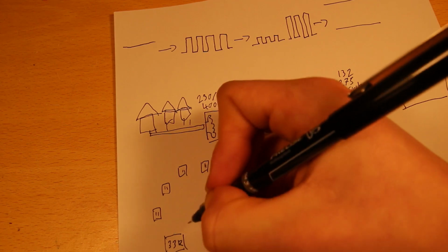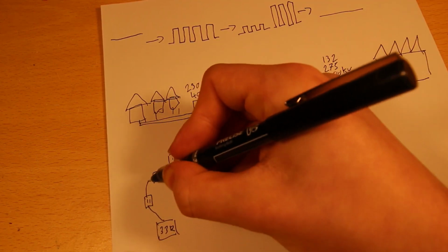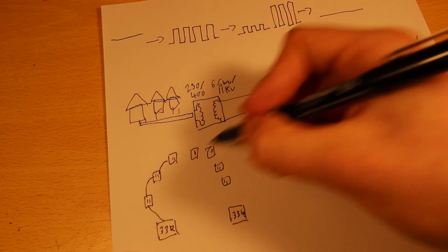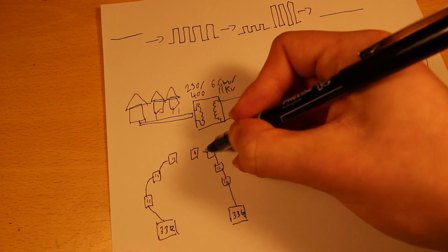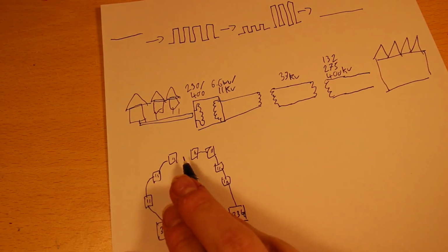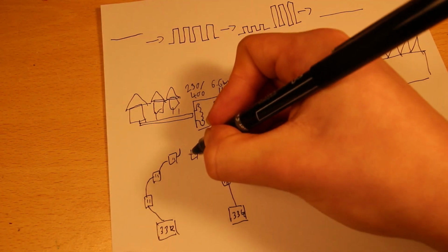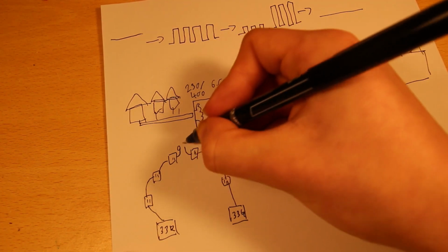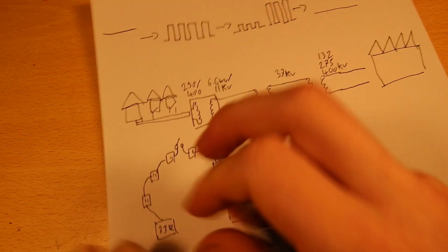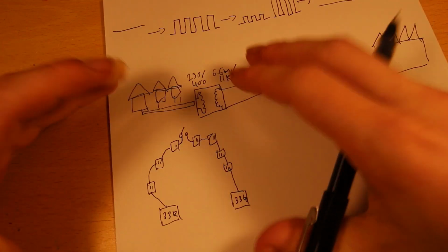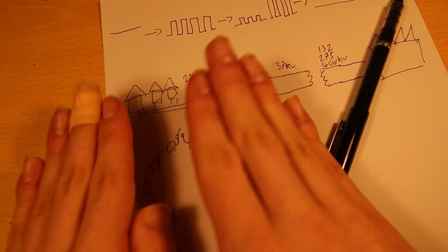What would happen is the wire will come out of this substation, it will go to here, and then it will loop like this. And then there'll be one coming from here, and it will loop like this. And then at some point in between these two substations, there will be a cable that comes out of that substation and one that comes out of that substation, and there will be a switch here, which is normally open. It's called a normally open point. And under normal circumstances, these two are completely independent.